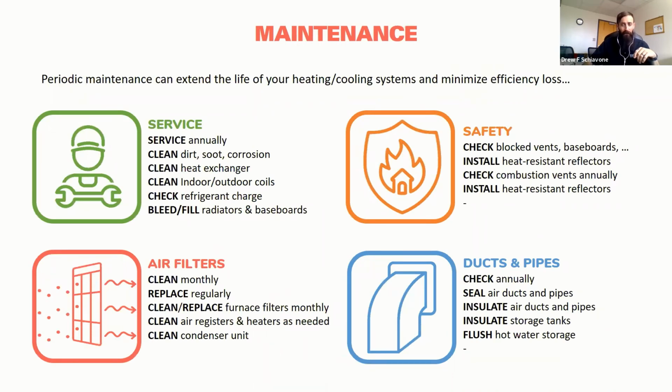Maintenance, and I'll just quickly touch on these. I recommend servicing all of these types of systems annually. There are some cleaning and work that you can do yourself, but a lot of it will have to be contracted out, and you can usually have a tune-up for fairly cheap. The air filters are things that you can replace yourself. Check those regularly, whether it be your furnace or air conditioner or other system. Typically, you're going to replace those once a month or every 3 months, depending on how heavy that seasonal use is.